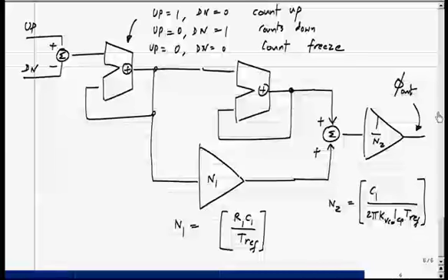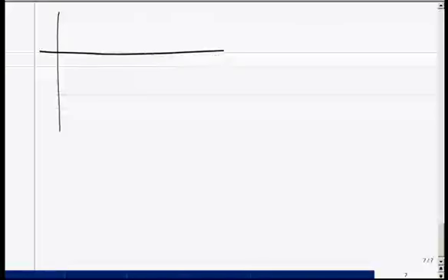The output will be some number that represents the phase. It is not necessarily an integer. So this is phi out of n. Now to complete the digital implementation, in this case we don't have a VCO. We don't apply this to the control voltage of the VCO. Instead, what we will have is a set of phases. So instead of the VCO, whose phase can be changed by its control voltage, we will have a fixed set of phases, at the desired frequency.